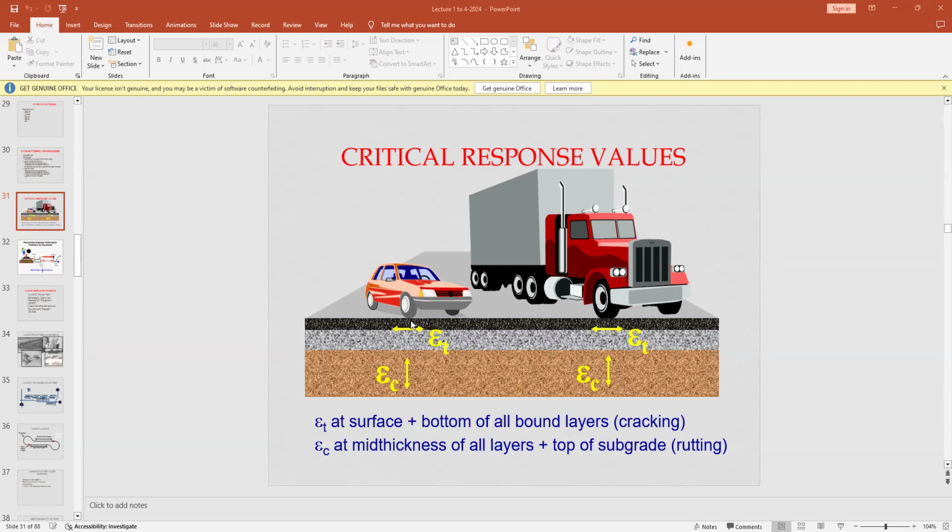So that's why we can't control rutting. And when I was talking about, say, 8-ton load and 12-ton load, I mean for 8-ton load you have a lesser thickness. For 12-ton, you may have more thickness. And for maybe 20-ton, you may need more thickness.